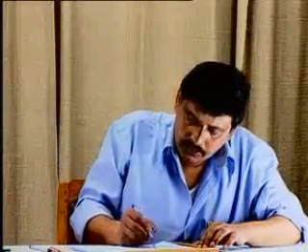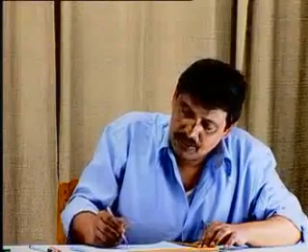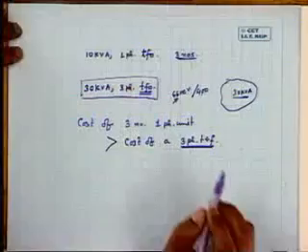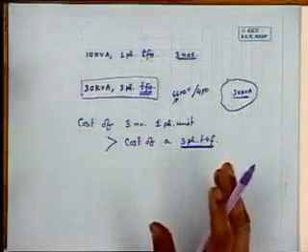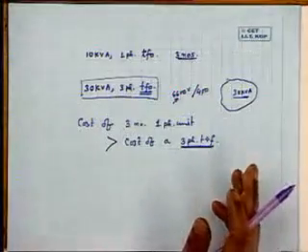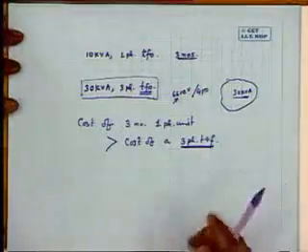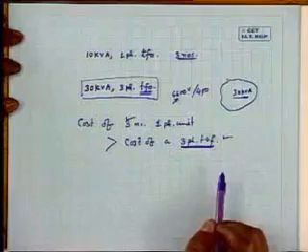So you remember that the cost of three single-phase units will be more than the cost of a three-phase transformer unit. Obviously, of course, the three-phase transformer unit as such, of 30 kVA rating, will be definitely costlier than a 10 kVA transformer. That is okay, understood, because 30 kVA etc. is there. So either of these two options are there, either this way or that way.